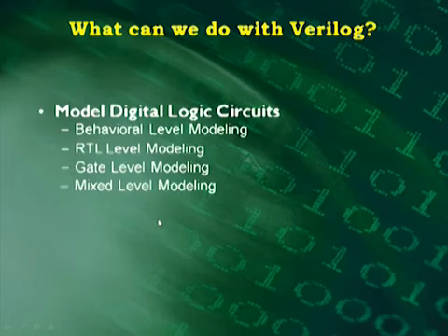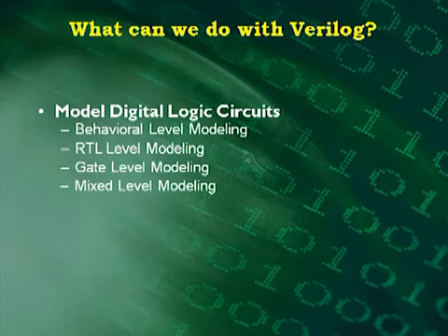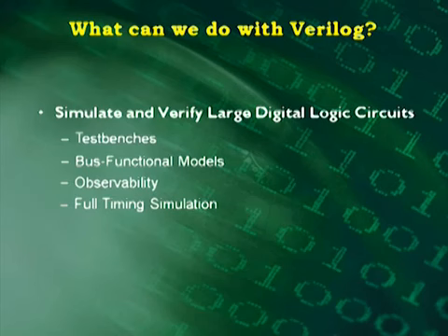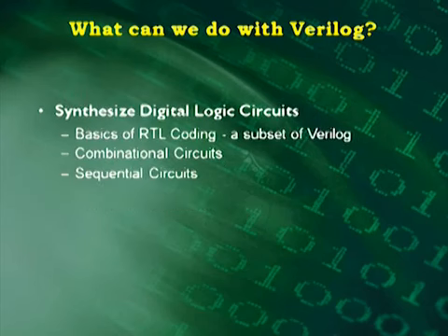So in modeling our digital logic circuits, we can do that in a variety of ways. We can write behavioral level models, or RTL level models, gate level models, or mixed level models. And I'll go into more details on that in a minute too. In simulating, we can write test benches to help us, and bus functional models that will help us verify our design and see that it's working properly. We're getting the right signals in and out, the right timings. We can do full timing simulation actually with Verilog if we want to.